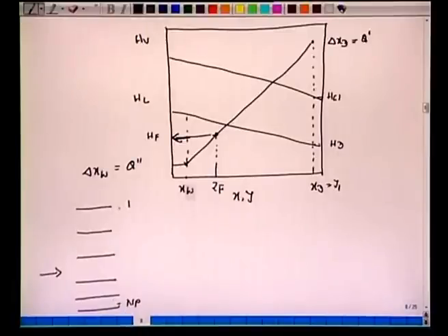All right, now we have this vapor leaving here, which has mole fraction Y1, which we have marked here with the enthalpy HG1, and we have the liquid which leaves with composition X1. Mind you, XD is the same as X0, the mole fraction of the reflux which goes into the column. So this is X0. Y1 and X1 are in equilibrium. Similarly, the vapor which leaves plate 2 with composition Y2 is in equilibrium with the liquid which leaves stage 2. So these two are in equilibrium.